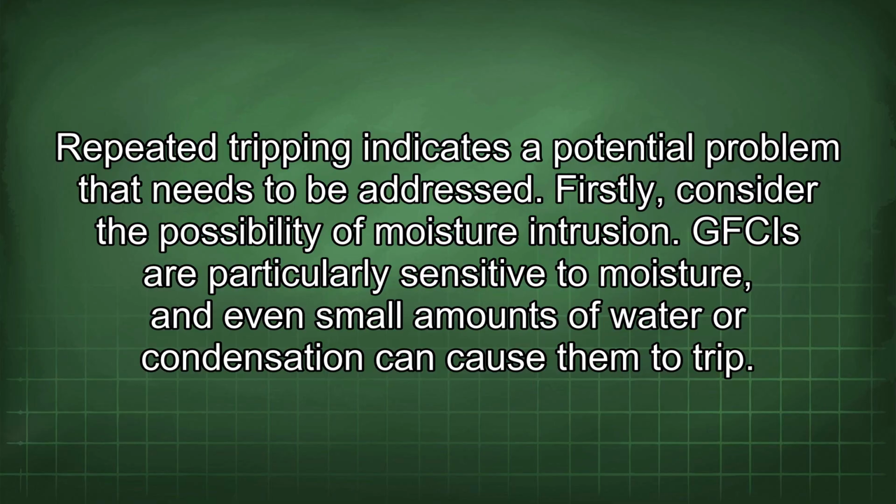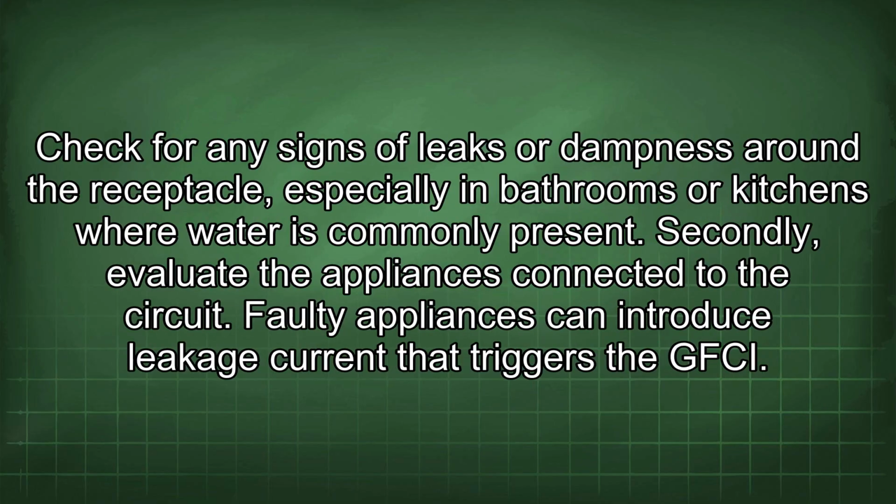Firstly, consider the possibility of moisture intrusion. GFCIs are particularly sensitive to moisture, and even small amounts of water or condensation can cause them to trip. Check for any signs of leaks or dampness around the receptacle, especially in bathrooms or kitchens where water is commonly present.